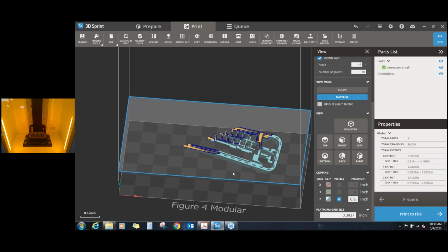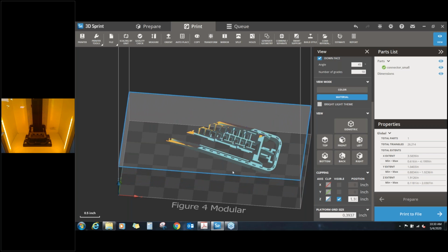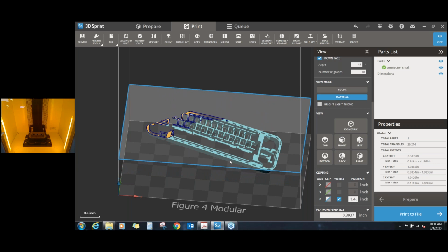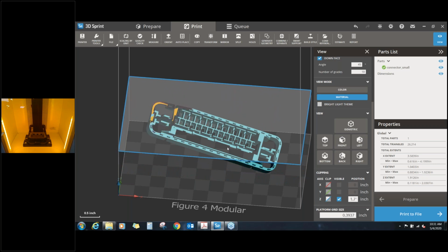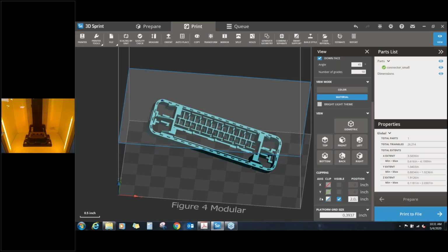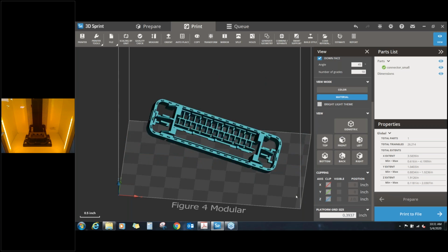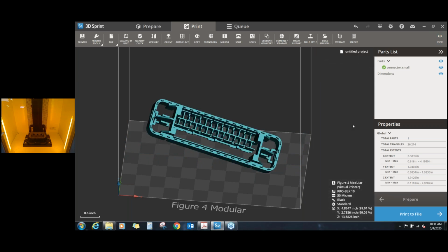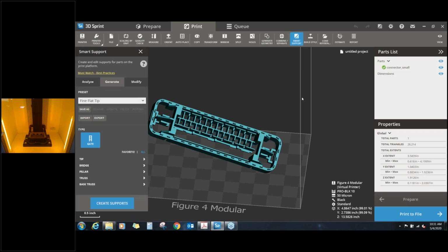And this is just going to ensure that the adhesion force, as our build plate dips down into the resin tray and makes a very low contact with the film underneath, when the tray pulls up, it needs to overcome this adhesion force. And the lower surface area that you can do, the better results that you get.